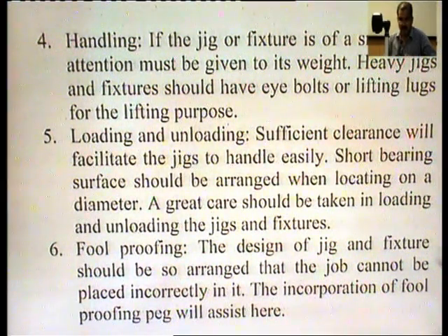So, sufficient clearance should be there so that a job, a workpiece can be loaded or it can be unloaded easily within the jig or fixture or out of the jig and fixture.